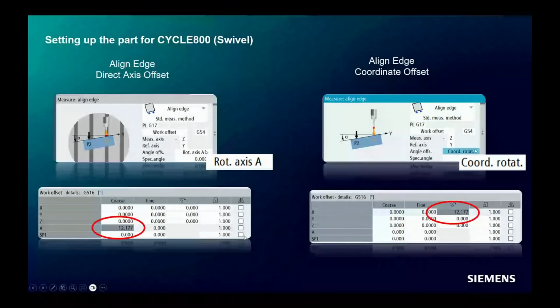Yep, and then we got another one here. Can you move the cutter from Y minus to Y plus, or Y plus to Y minus, while milling a profile cam track around a tubular part? Yeah, I think this is no problem. It's just depending on where you're at with your work offset. You can have it in the center. This one might be in the center of your part.